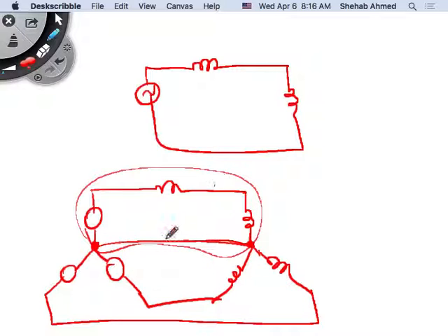So I can solve my single-phase equivalent circuit that way. But if there is current here in the neutral, so an unbalanced case, if x here does not equal x here, this is x1, x2, and x3, and they're all unequal, what do you do? You can use your circuit techniques, what you know about circuit analysis, and of course you would have to do three loops here and solve your loop equations.